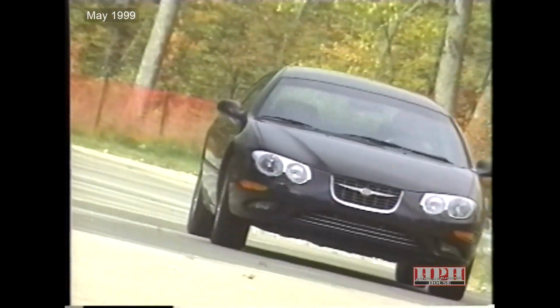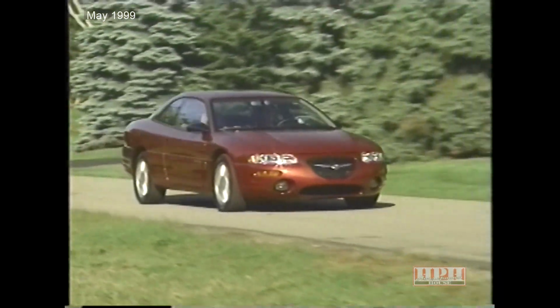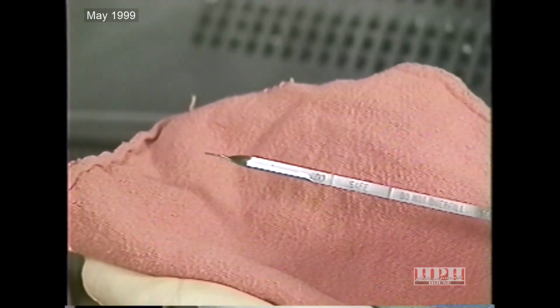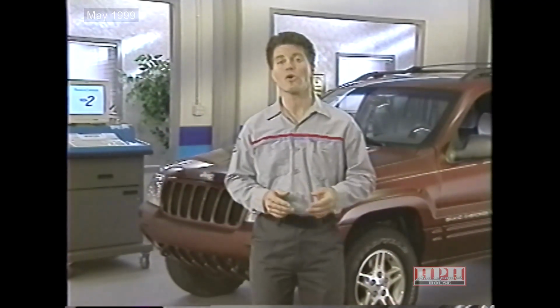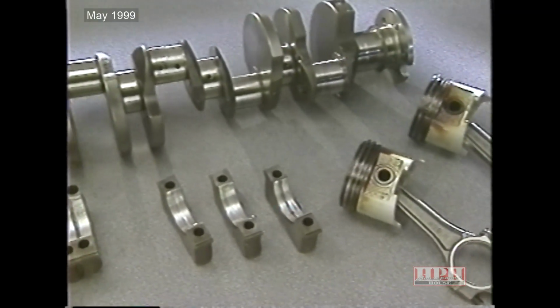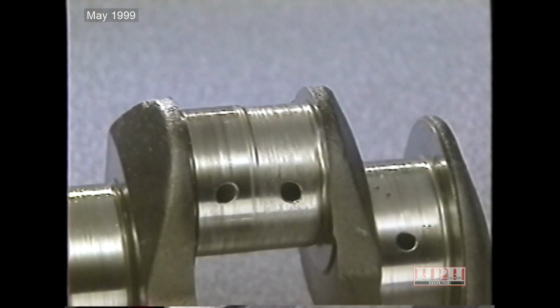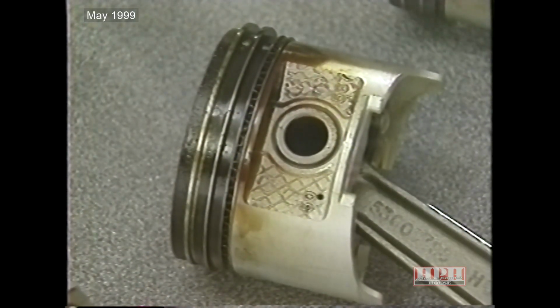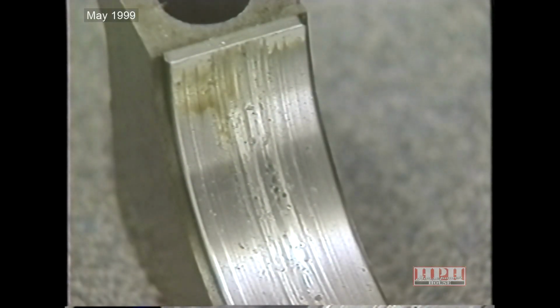Any time a vehicle is driven with too little or too much engine oil or transmission fluid, a number of things can go wrong. For instance, too little engine oil will lead to internal engine problems. This is because the oil can't circulate properly through the engine's lubrication system. As a result, internal engine components are subjected to increased friction and heat. If a vehicle is driven for an extended period of time, accelerated engine wear or damage could result.